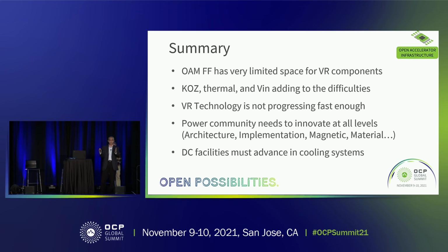This reminds me of a time when we moved from 5 to 12. It was the same thing. We came with the 2 to 1, 12 to 6, and then we took a buck converter as a second stage. And we are in the second renovation now. We're going from 12 to 48. Many designs take a first stage converting 48 to 12 and take a buck again. I think it's time to change that.